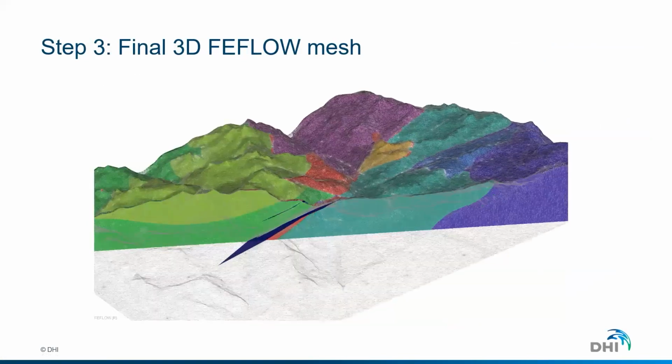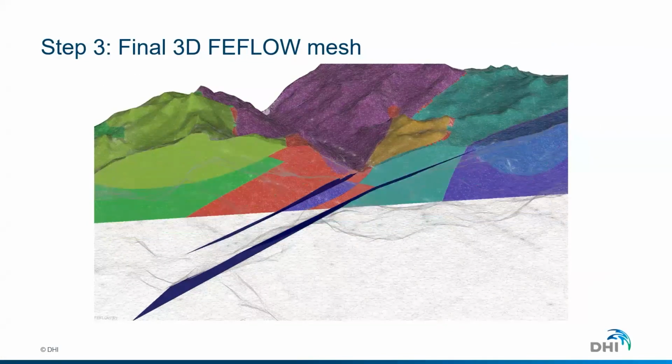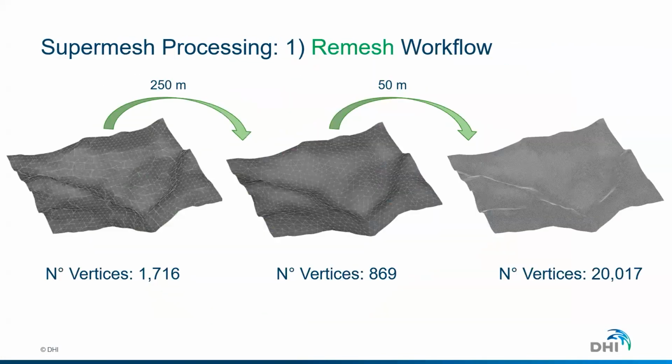after the repair or remesh operations. So to demonstrate these two workflows, I have a number of slices, and the first one is about the remesh workflow. You can call this remesh in FEFLOW, and so far how it works is it will remesh all the surfaces that you have. So it could also be seen as a tool for simplifying geometries or for refining geometries.